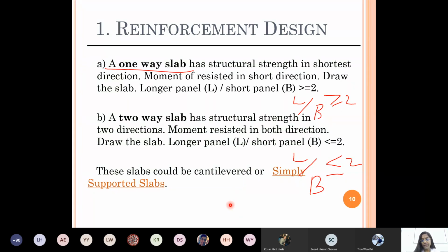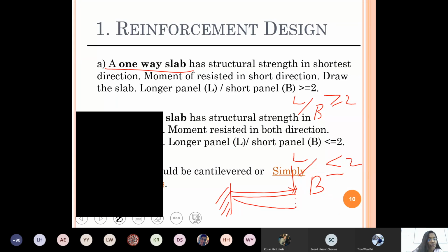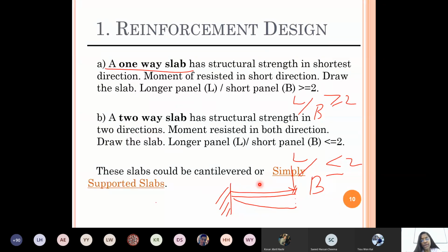Okay. And if you want, I can draw and show you a cantilever beam for semester 1 people. The support will be like this. The beam will be standing like this. Okay, so there is a chance of loading, right? If it is uniformly distributed over the beam, it is good. But if it is a concentrated load acting at this point, there is a sagging moment. Sagging failure will be like this. So you need to address these types. This type of beam is called a cantilever beam. You have to design according to the type of beam.